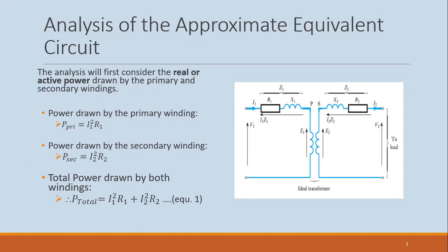So those transformers are on the poles outside of your house, outside of your gate, on the line. Once load is taken, the voltage will fall. So at your home, you might see low voltage sometimes if too much load is on the transformer. Say the transformer is not properly sized, or load increases over time and they did not change the transformer, then you will start to see low voltages at your house.